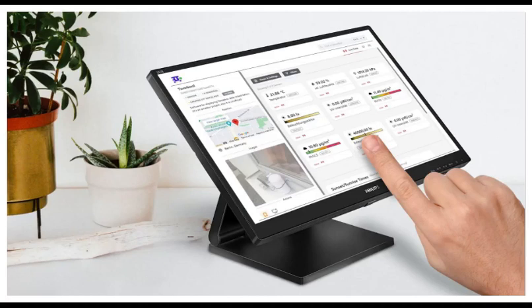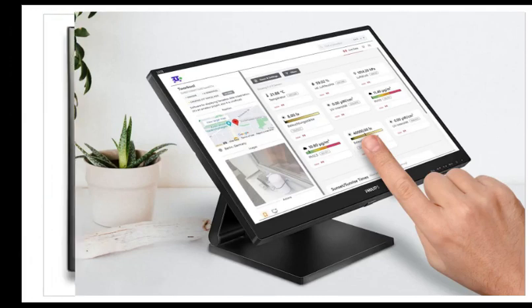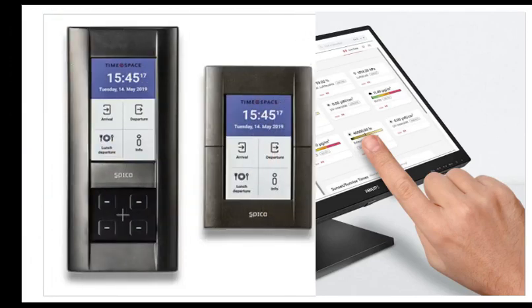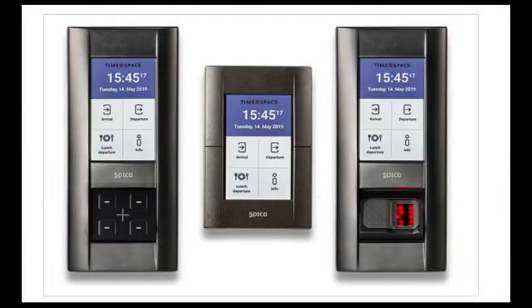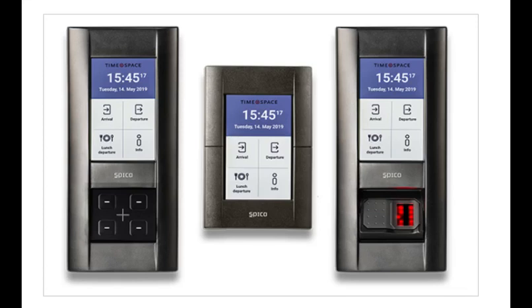A resistive touch screen panel comprises several thin layers, the most important of which are two transparent electrically resistive layers facing each other with a thin gap between. The top layer, that which is touched, has a coating on the underside surface. Just beneath it is a similar resistive layer on top of its substrate. One layer has conductive connections along its sides, the other along top and bottom. A voltage is applied to one layer and sensed by the other.